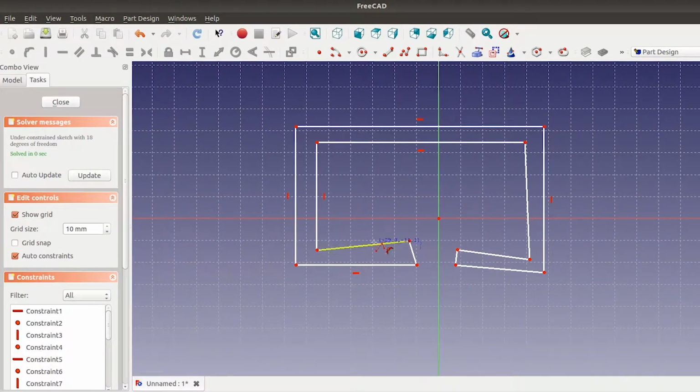First point, let's make all these lines horizontal. For that, we select them, and on the constraints, we choose horizontal. You already know this. So let's select all of those that are not horizontal, and check horizontal. Now let's take the vertical ones, those that were not yet vertical, and we choose vertical.